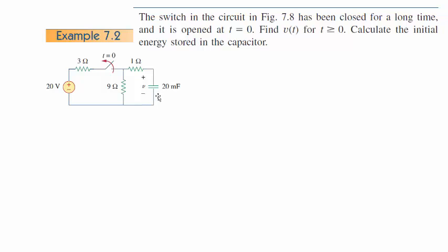And remember, when the capacitor is fully charged up, current no longer flows in that circuit. So at that point in time, after actually more than 5 time constants have occurred, after sufficient time has occurred for this capacitor to get fully charged up, then it appears as an open circuit. It is something that cannot hold any more charge in the circuit, and it's waiting to have a discharge event.